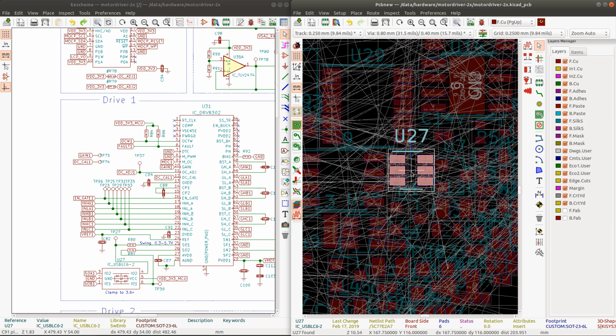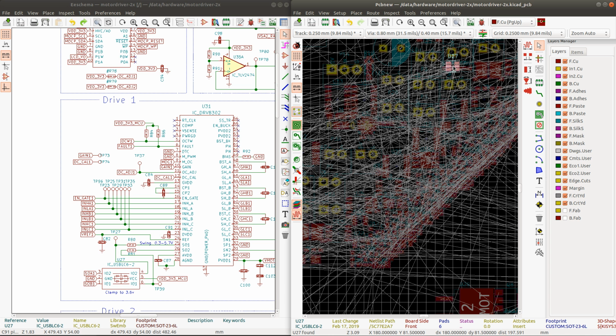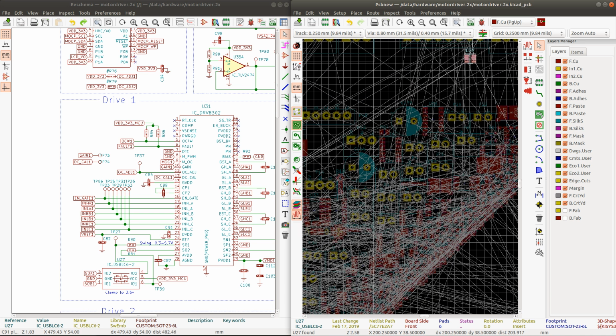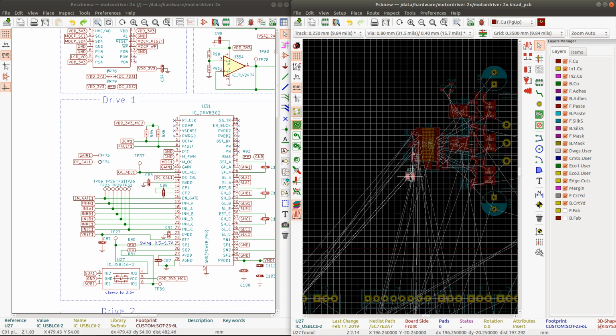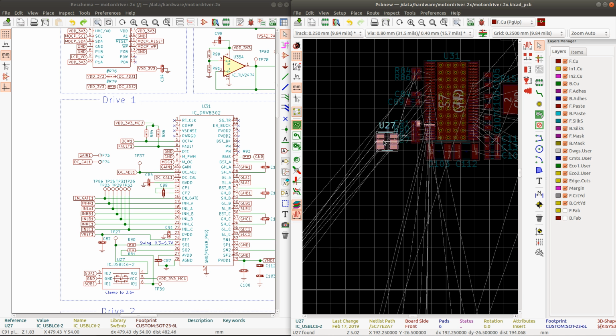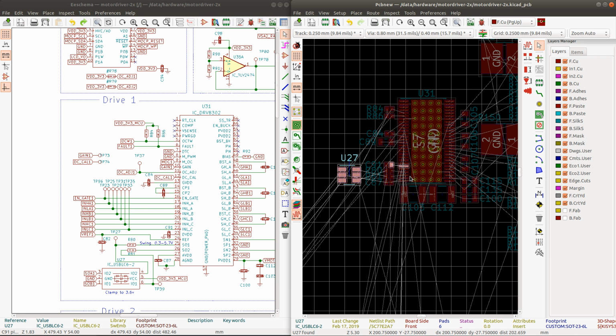So what's gonna happen, because of the voltage swing, this chip has a built-in current amplifier. It is connected through these pins, the current sensing output 1 and 2, and these go to the MCU. Now, the datasheet specifies these pins as being from 0.3 volts to 5.7 volts, which is way too much for the analog inputs on the STM32.